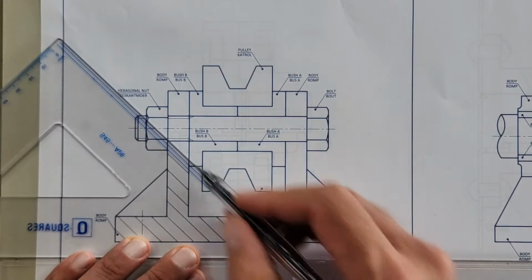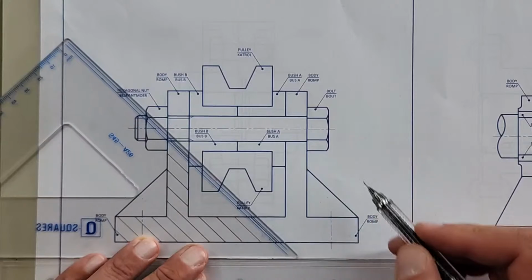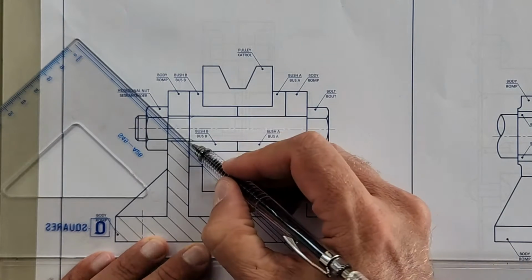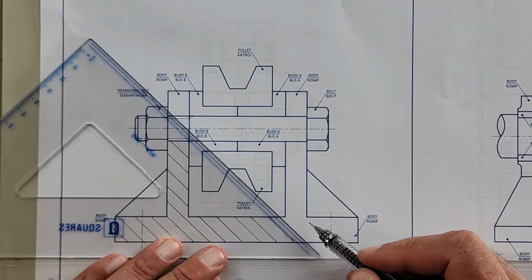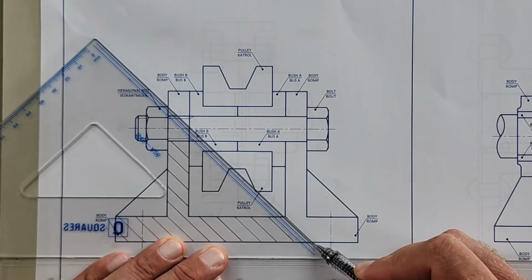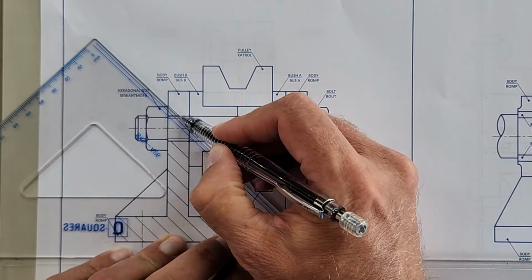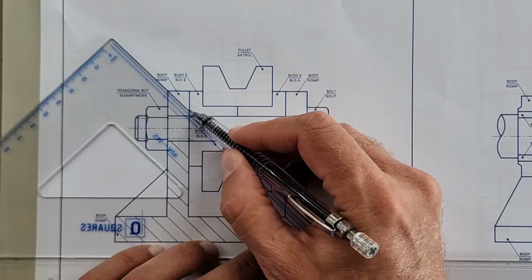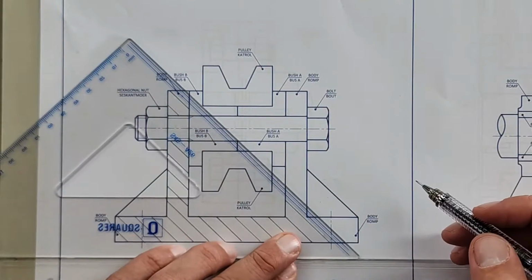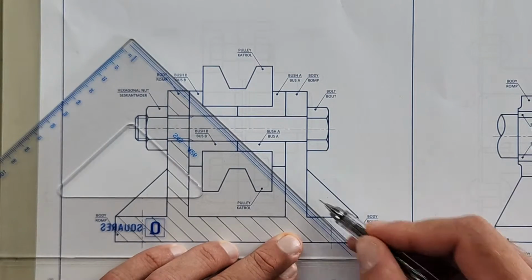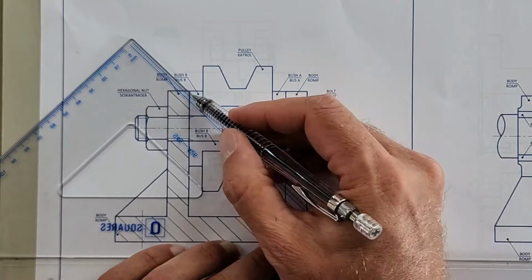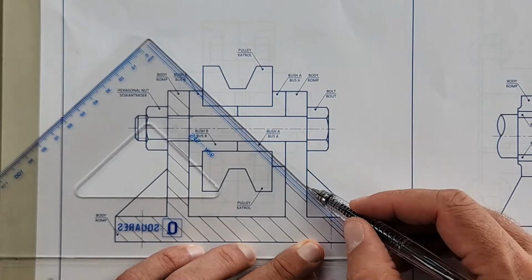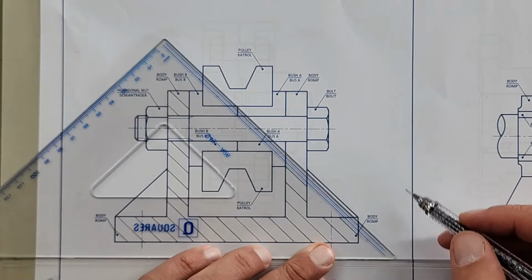Okay, so you will lose marks here if this hatching isn't done consistently all the way through. So please help yourself out and make sure you do this with me, spacing it evenly all the way through. Okay, it's one casting, and so this direction stays the same. It's one body, it's not different parts here. It's one full body that we're using.